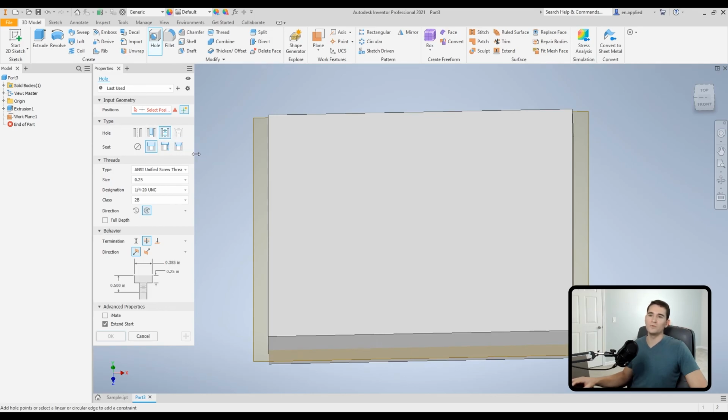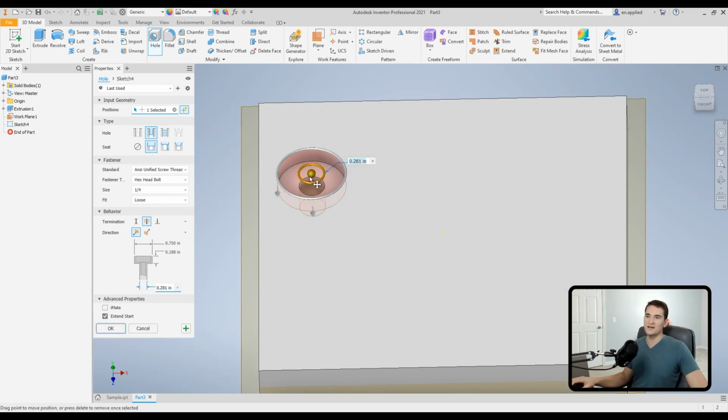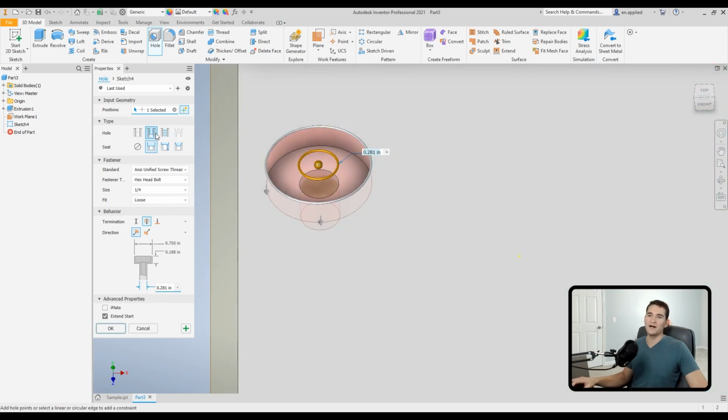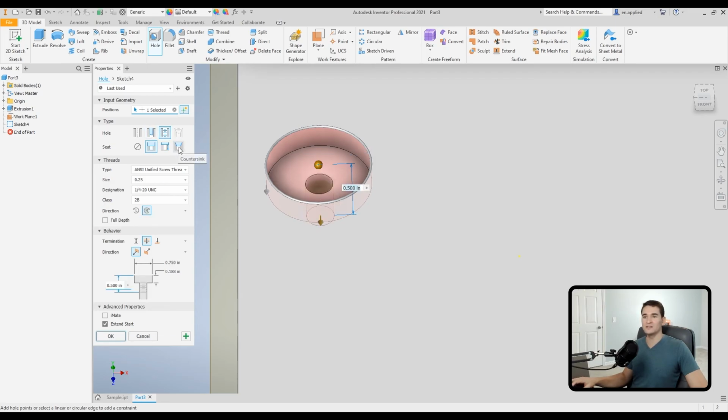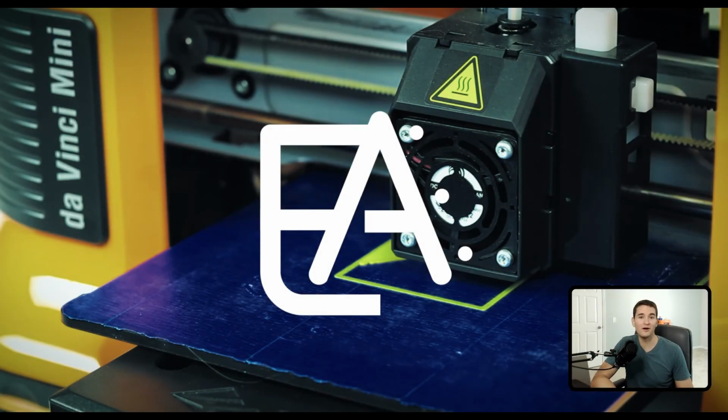So let's say we want, instead of a simple hole, a clearance hole, but counterbore, we can always do that. So, we can size that however we need and combine this with a clearance hole type, or we can switch it to a tapped hole and let's say a countersunk opening as well. So, again, you can mix and match things depending on your design needs. And that just about sums up all of the hole functions and how you would use this appropriately in your designs. That wraps up this segment of the Autodesk Inventor part modification module, where we took a look at the available hole tool.